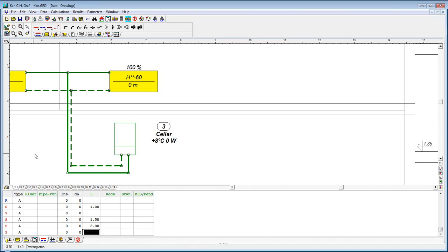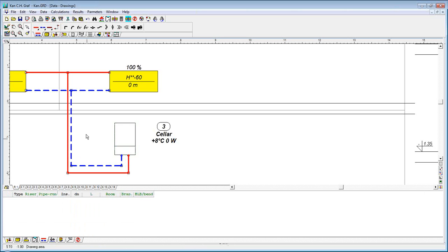Okay, so as you see, quickly I entered the lengths of the horizontal pipes, and then it may happen that there are some bends that we can't see on the diagram, so we've got this possibility here to add some additional bends that are not seen, because all the bends that the program can recognize from the drawing, it can do automatically. We only have to add these additional ones, because as you see in the diagram, it may be drawn as one pipe, but in real life, in your boiler room, it may happen that it goes around the walls and that there are these two additional bends.